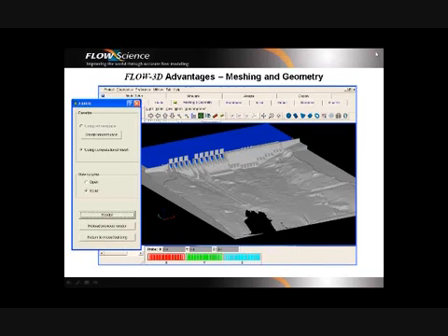We are back here. In Flow3D, we use a structured mesh that overlays the imported geometry. Generating a mesh is as simple as overlaying it on the geometry and defining a level of resolution. Our proprietary FAVOR method defines fractional areas and volumes within individual cells, enabling smooth and accurate representation of the complex geometry.